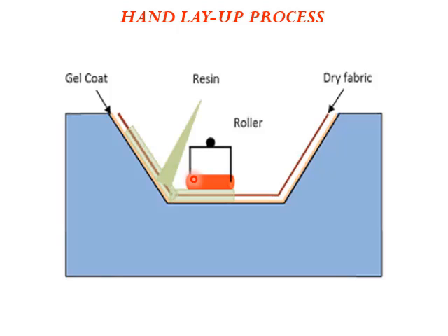So in order to ensure that, the resin is mixed with the catalyst normally. Then after all this process, the mold is allowed for a certain duration to get cured. When the process is complete, we are going to take it out with the help of a gel coat, and we are going to check for proper bonding of the resin with the reinforcement material. A simple process. Most of the composite materials are processed initially with this process only.